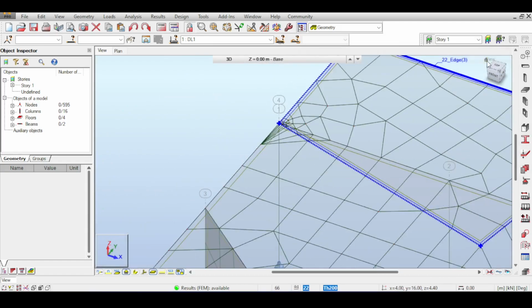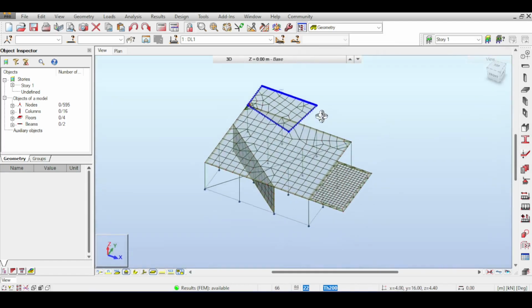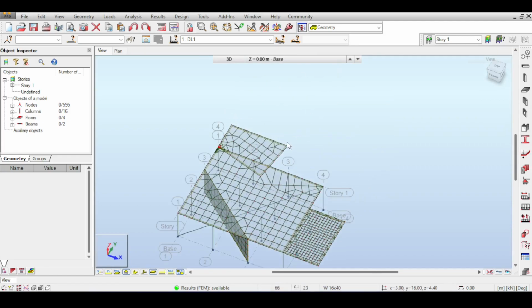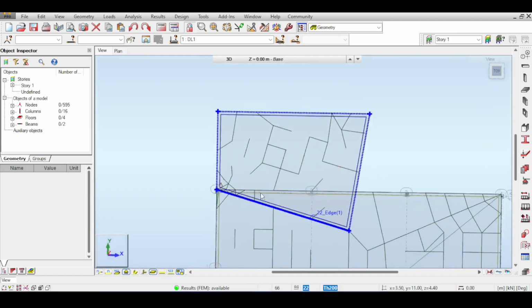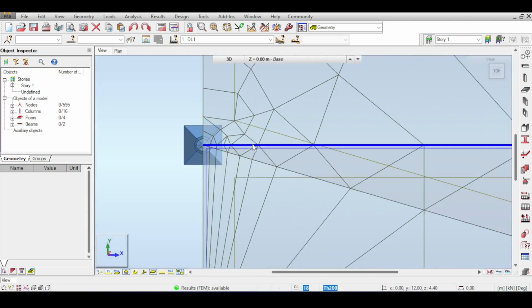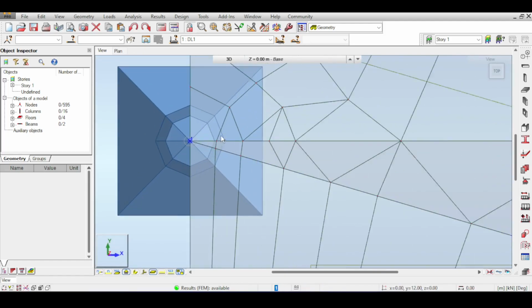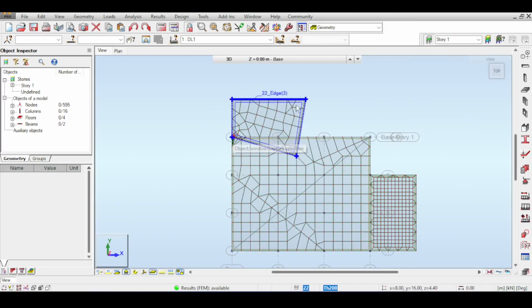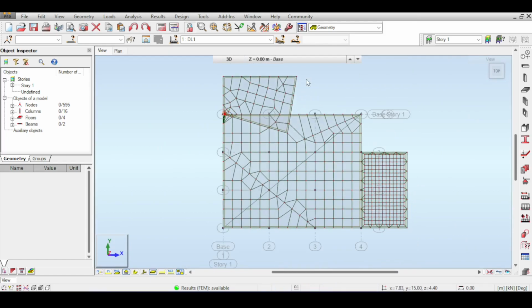Now, back in the day in Robot 2010, we had a very quick idea to understand where things can go wrong whenever I have overlapping panels. Whenever you have overlapping panels, you will see suddenly an abomination of points because Robot tries to weave those points together as best as it can and ends up with a plethora of points here, which will immediately direct you to a problem in your mesh that you have overlapping panels.